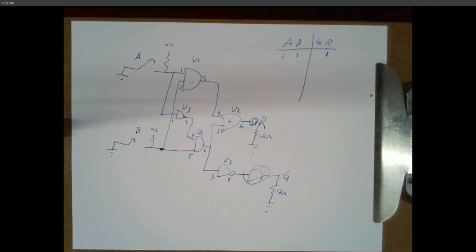But here's a combination. If I have both of these open, the red light should be on. Okay, and you open up these switches and the red light is off. So how do you figure out what's going on? Grab a multimeter, get some alligator clips, take the ground probe, the black one, connect that to ground somewhere on your circuit board.